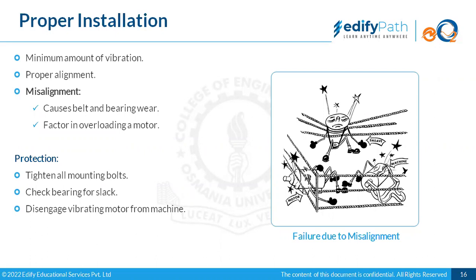Even a small issue here and there, in a high rotating motion process, this small misalignment will keep on multiplying with the span of time, and it would become big enough to either cause damage to the motor or to the machine that it is moving, or it could even hamper the operators who are working on this.